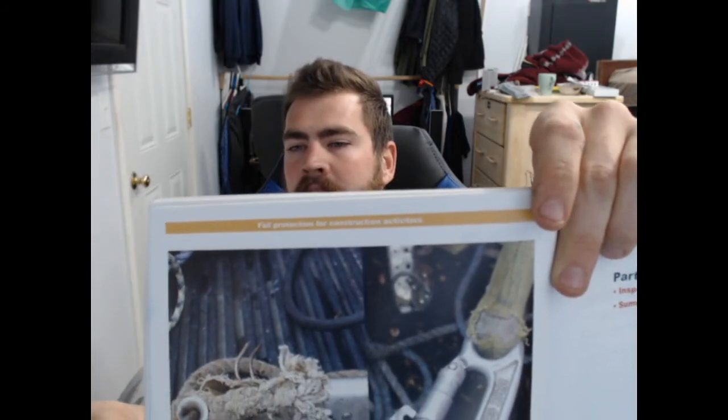We're down to Part 8, maintaining equipment. This is some nice little stuff. So you can see the D-ring is not functioning correctly, and the fall protection rope seems to be having some frayed areas on it. So we can see clearly that we have issues here with this equipment.